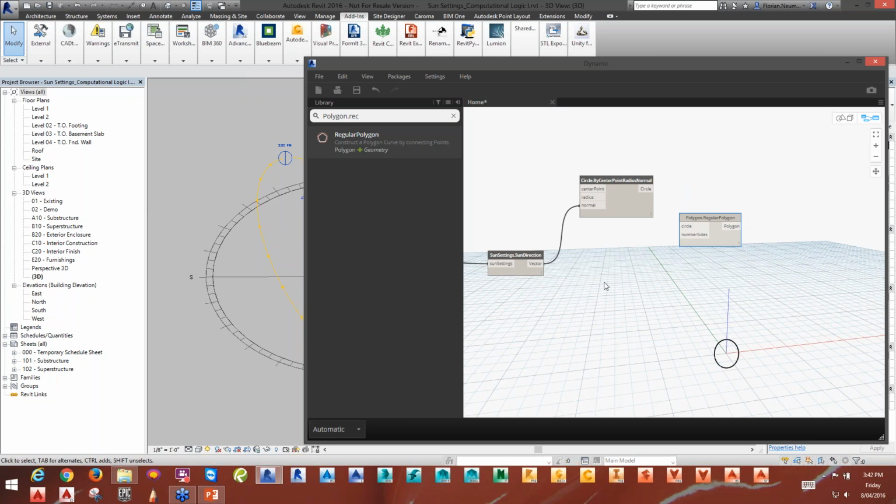We want to have some number of slices, hence what we simply can do is either use a code block, or I use maybe a number node, and I just type in, for instance, here the slices. My circle I connect with circle again. So you see it's actually playing like Lego, where the blocks actually fit together, circle with circle, number with number, normal and vector together. So that's actually pretty cool.